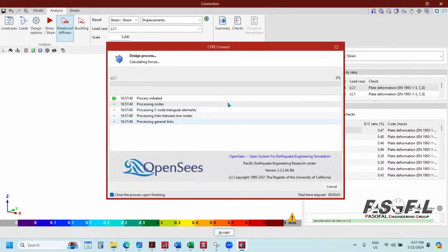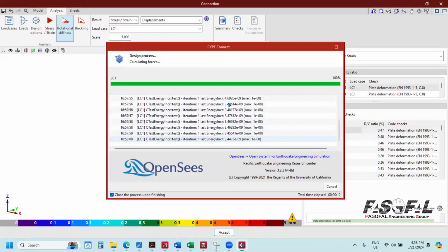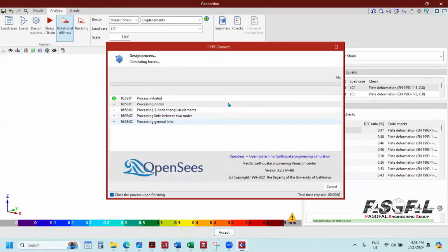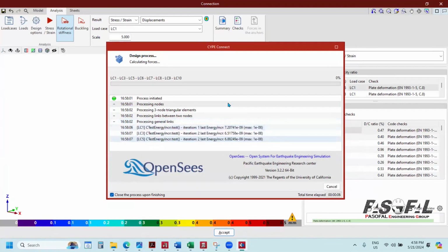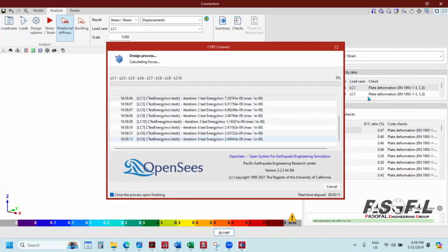We know that this type of analysis is a rigid connection. In this connection, we are using the end plate and the software should come up with the rigid connection behavior. Let's see. But not all the connections are simple like this to understand the rigidity of the connection. Sometimes, for example, you have some connections maybe like this. Maybe here you have the column, and then here you have, for example, one beam with a little bit of gap.